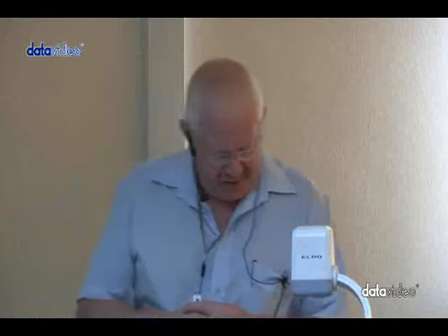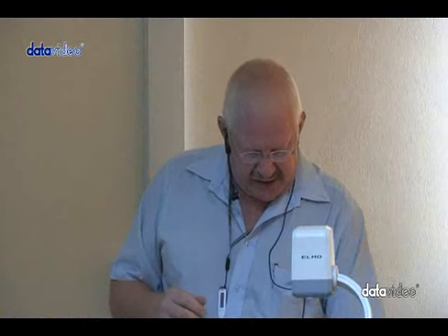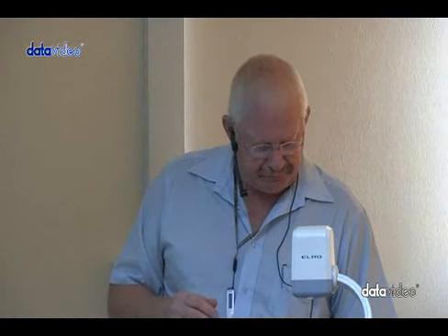Please note that the value of r'e is quite small. It's normally between, I would say, 5 to 20 ohms. So if you calculate the value of r'e and you get a value larger than that, you must know that you've made a mistake somewhere. So that's one way to check your answers, to know what type of answer you expect. Alright, that is determining r'e then.